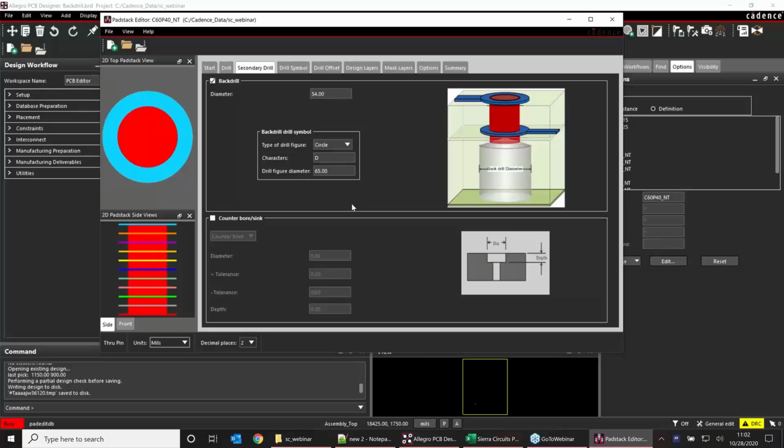That is one thing. Another thing is the prepregs available. The prepregs are generally available from thicknesses of 2 mil onwards. A very common prepreg thickness generally used between layer 1 and layer 2, especially when you want controlled impedance traces on layer 1, the outer layer, of 50 ohms and 100 ohm differential, should be around 3 mils. If you model all those, depending upon the material, it will generally range from 3 mils to 4 mils.